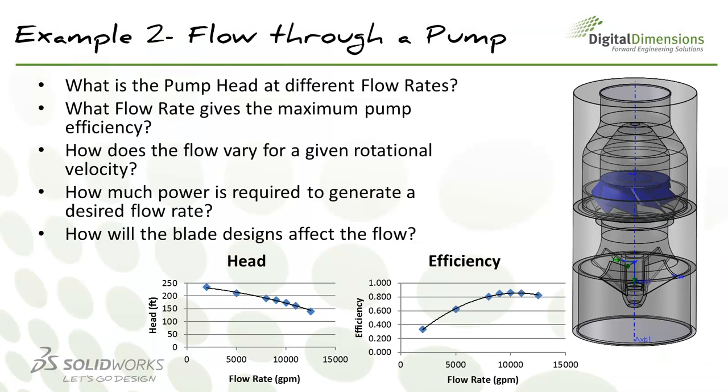For our second example, we're going to talk about how to simulate flow through a pump design. Presented are some of the most common questions you may ask whenever you're in charge of designing a pump, such as what is the pump head at different flow rates? Which flow rate gives us the maximum pump efficiency? How will our blade designs affect our flow fields and the efficiency? All of these questions can be sought after and visualized through SolidWorks Flow Simulation.